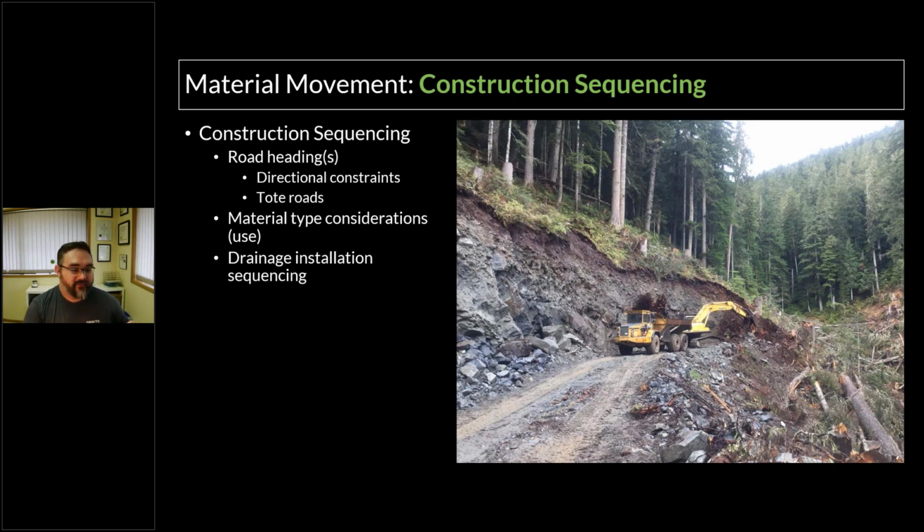So if your mass haul is going above the zero line in this kind of ground, that's not an easy thing to do, because you can't just move it forward as you're excavating it. So you'd have to do things like temporarily store it. So you have to understand that beforehand, before designing these spoil sites, of exactly when you can do it.